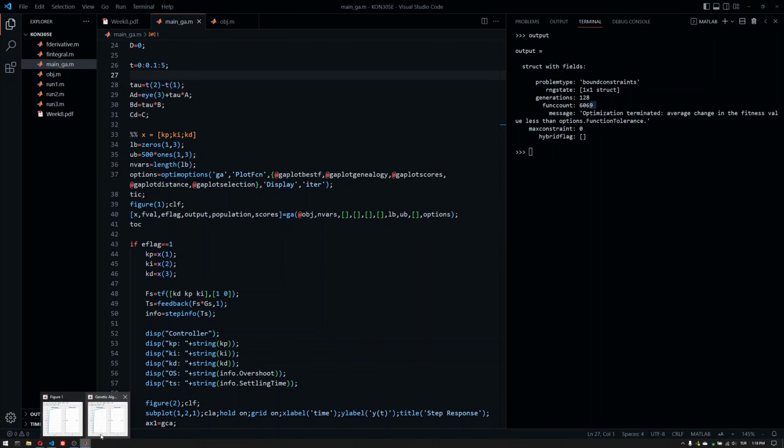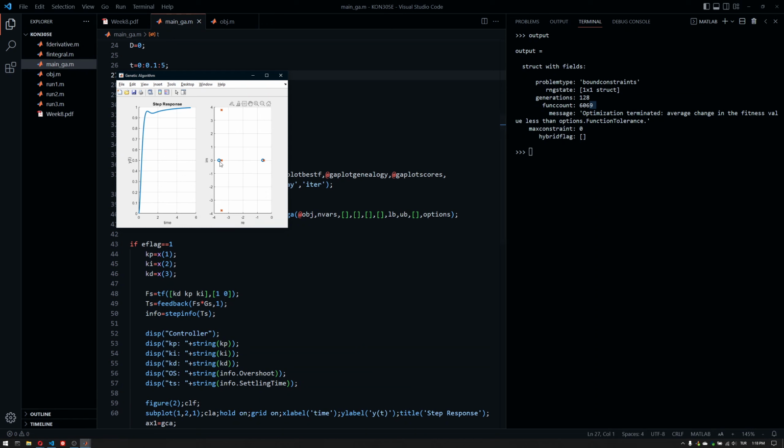By the way, I can also comment on the results here. We can see that there are some almost pole-zero cancellations. The optimization hit a boundary here. It tried to get rid of 2 of the poles with the zeros of the controller, and it is then left with basically a pole pair, which we call the dominant pole assignment. It's going to be the topic of the control system design lecture.